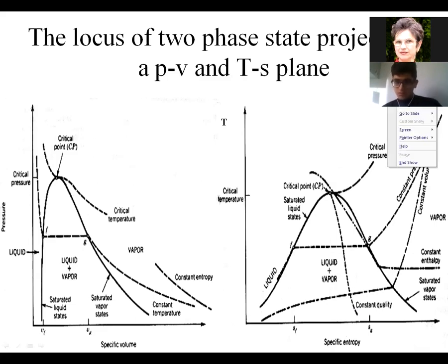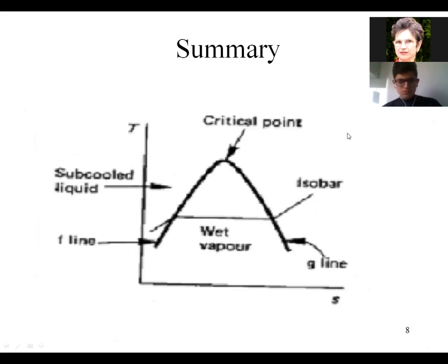Okay. So we resume. What you have to know: here is a zone with subcooled liquid. Here is liquid at equilibrium. Here you have wet vapors, meaning a mixture between liquid and gas. Here you have saturated liquid, saturated vapors, and here you have what? Superheated gas. Yes? Okay.